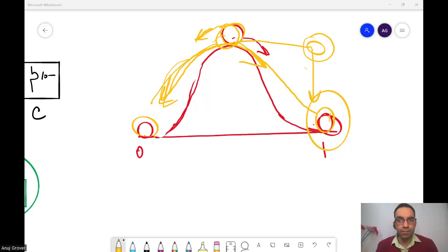Sir, but even there I am connecting the bit lines to the gate, so capacitive coupling is coming in. Capacitive coupling आ रही है, but this is about Q point recharge. This is not about capacitive coupling. This is about recharging the sense amplifier input nodes that are close to the Q point. Okay. They are two very different things.